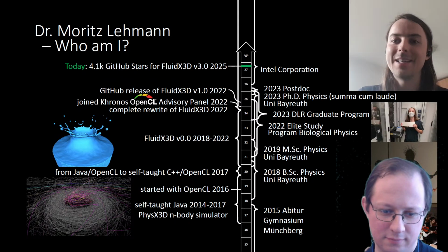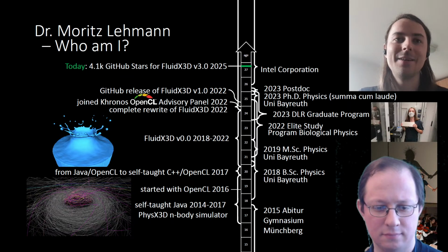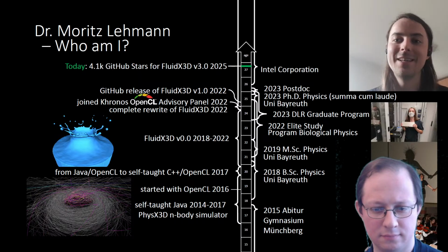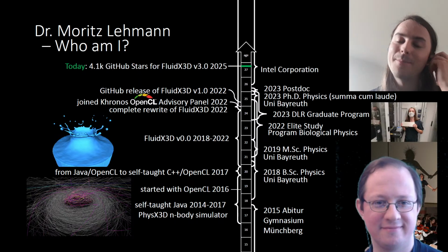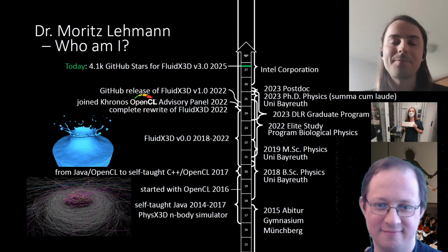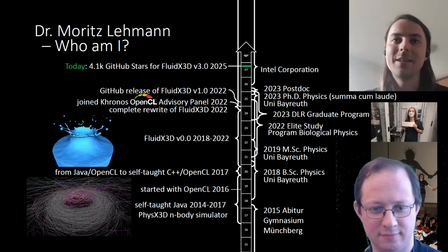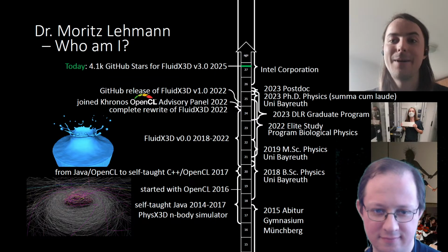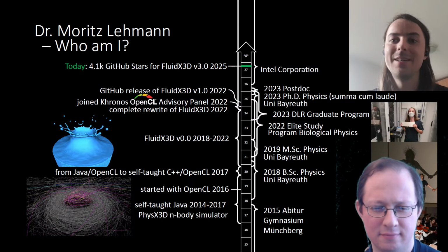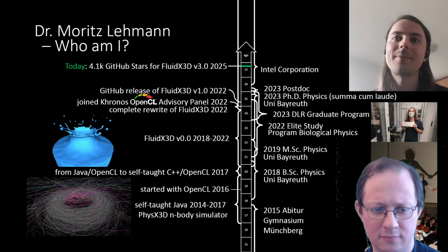So that was one of my motivations to start my own code and see if I can implement a Lattice Boltzmann any faster. And that's what I did. That is how FluidX3D became a thing. I just implemented the Lattice Boltzmann from the ground up in OpenCL. And within a few months, I had also ported over the blood cell model directly on the GPU, and it was like 20 times faster on the same hardware, just by eliminating this PCI Express transfer that the other software was doing.